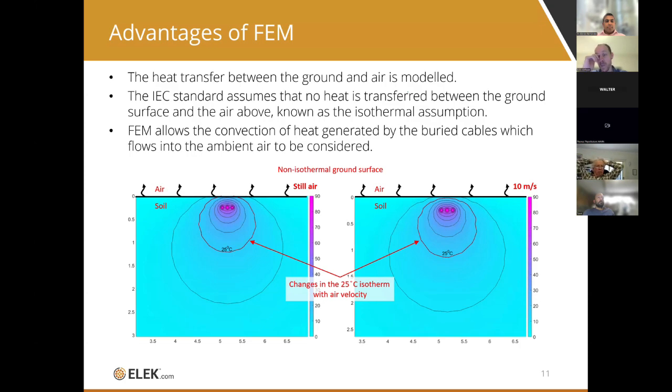So it's an input. We take the input of soil temperature and ambient air temperature. Is that correct, Edston? Yes, soil and air ambient temperatures, and we would also require to calculate the heat transfer coefficients. Either the software can do it, or you can enter the values. But it's much better if we just do that for the user, right? Yes. And it's an iterative process, right? To be accurate, yes. Because the heat convection coefficient changes with temperature, so it has to be iterative within itself.